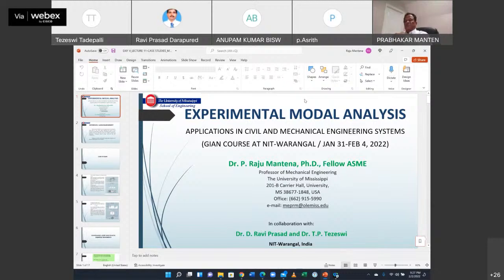They are a small system built into and attached to the cable. Due to gust winds, just like the Washington Narrows Bridge movement, at some forcing frequency those cables have a tendency to go into resonance. The tuned absorber changes that condition. The small dumbbell shed, which has the small mass and spring inside, attached to the original mass and spring, shifts that frequency so that the whole cable doesn't go into resonance. They are applicable at specific frequencies. You can't change them to broad frequencies. So that's how they are.